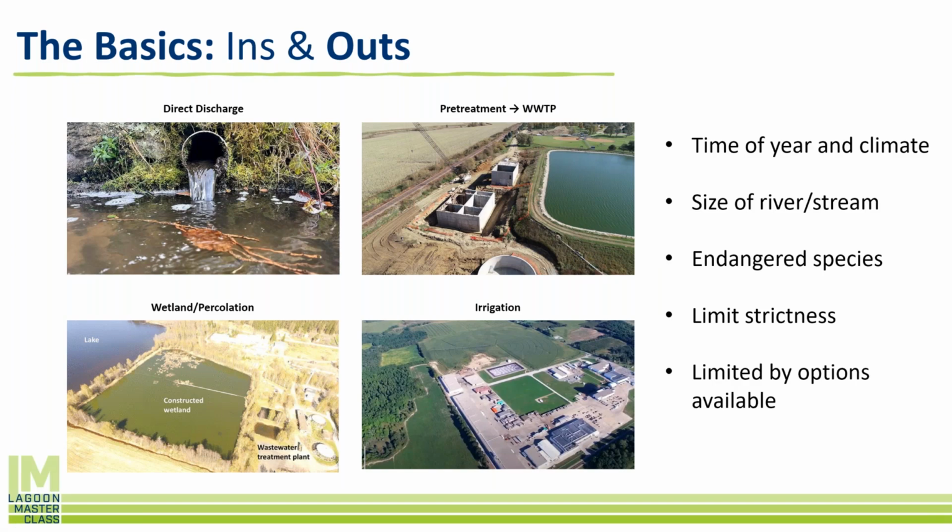And then there's essentially a non-discharge option where your wastewater lagoon or your treatment facility is essentially pre-treatment. We're trying to take the edge off the water. We see this more in industrial plants where their influent wastewater might be 1,000 milligrams per liter BOD and they're paying way too much money to treat it. They'll say, hey, let's design a lagoon system that knocks the BOD from 1,000 down to 200, and then we'll discharge that 200 to a conventional treatment plant. It might be a lagoon downstream. It might be an activated sludge plant for the municipality.